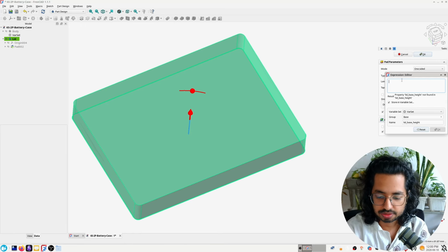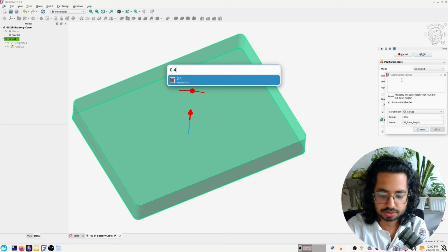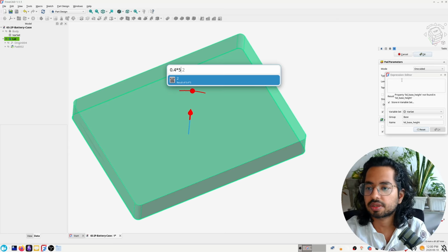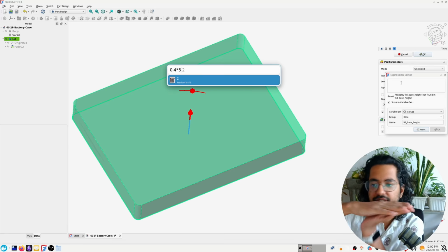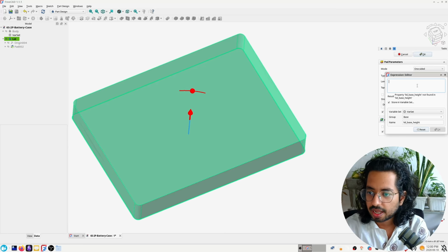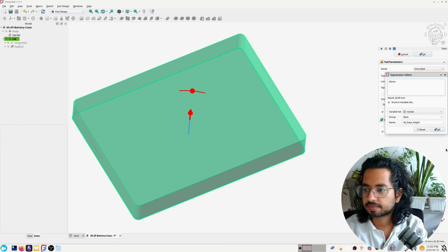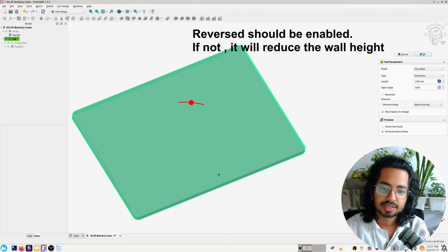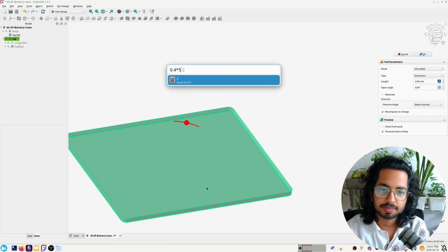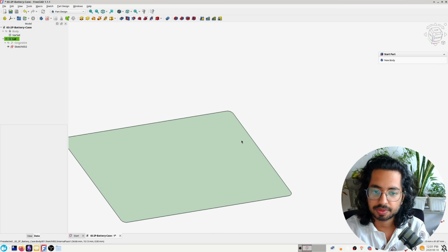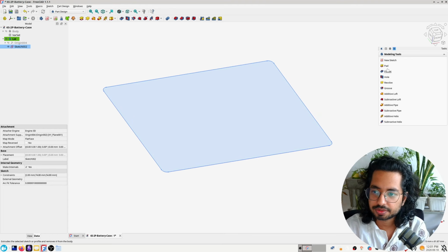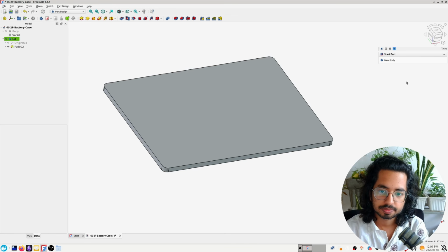So we are having 0.4 mm layer height, so 0.4 multiplied by 5. So we will have 5 layers slapped onto each other like a sandwich to get that height. Okay, 20 mm. Sorry, it's 2 mm, not 20 mm. I should have multiplied. Yeah, this is 2 only. 0.4 into 5. Yeah, perfect. Oops. I pressed escape, so let me do this again. And now we press OK.